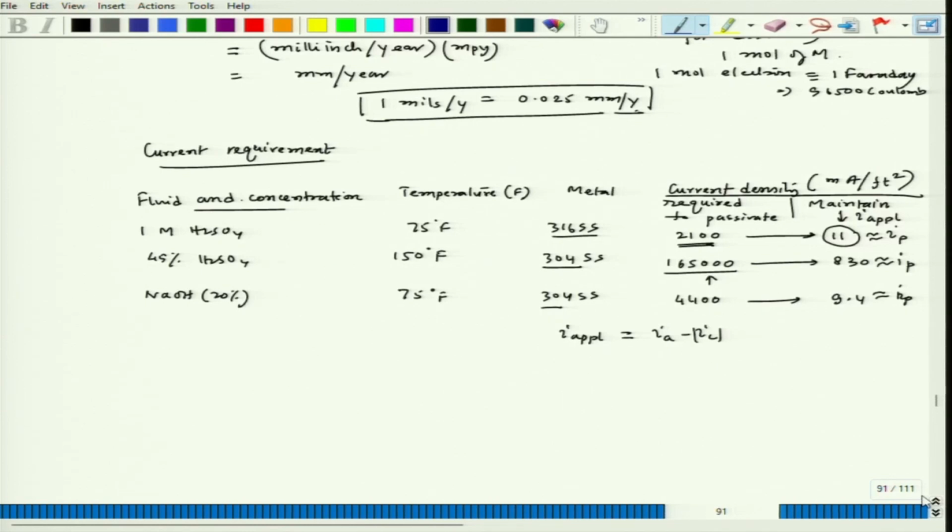or the protection. In case of cathodic protection, we simply say that this is the potential minus 850 millivolt criteria with respect to copper sulfate, the NACE criteria, that if the polarization potential of the steel in soil goes below minus 850, that means it should not go up. So, it should not be like minus 750 millivolt with respect to copper sulfate, then it will not get proper protection.